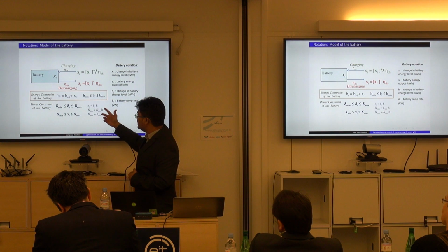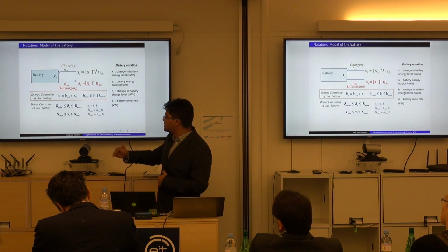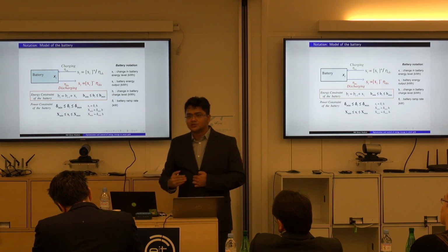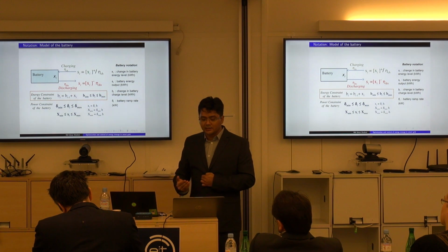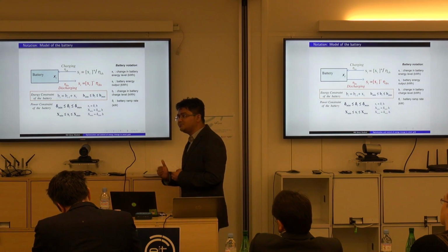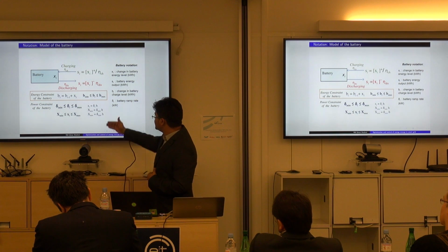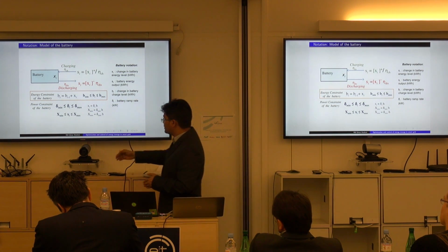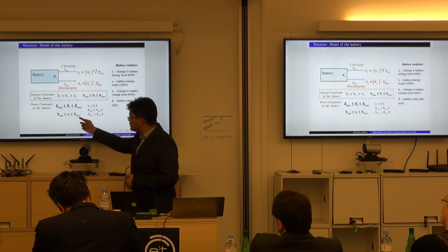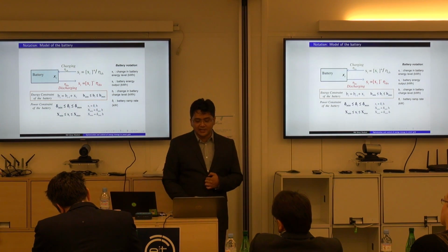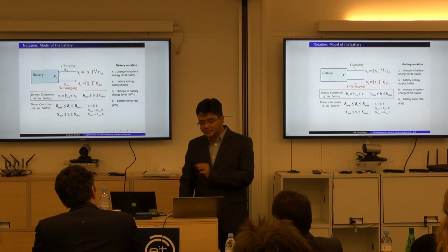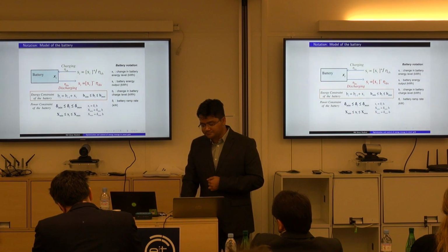There are two constraints taken into account here: the energy constraint, which bounds the battery capacity within a minimum and maximum. For batteries such as lithium-ion, it is prescribed not to charge beyond a certain level and not to discharge beyond a certain level. That puts those physical bounds. Then there is a power constraint, which is how fast the battery can charge or discharge. This is in units of power, and multiplying it by the sampling time of decision making, we get the energy that can be taken out of or fed into the battery at any time.